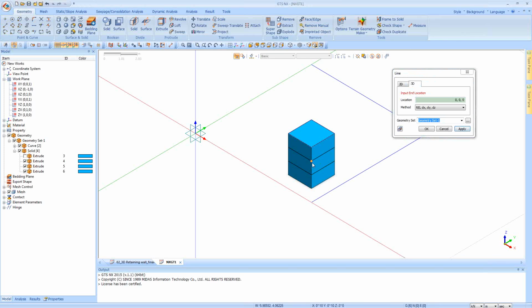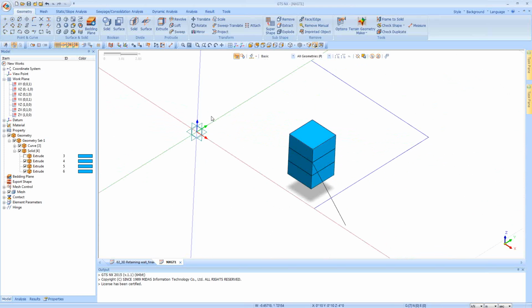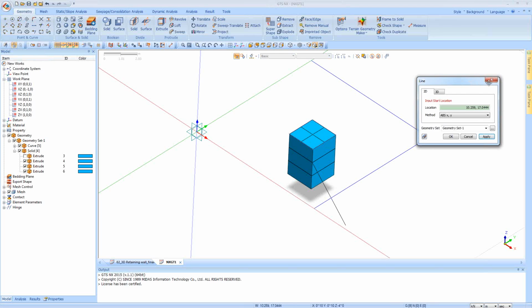So select the first point, and for the relative input you can give, let's say, the length being 3. So no movement in the direction of Y, and minus 3, say, the relative length. So the anchor is created. Similarly, you can create various lines, for example, supporting beams. So you can just create a line like this or like this. So this can be a supporting beam.